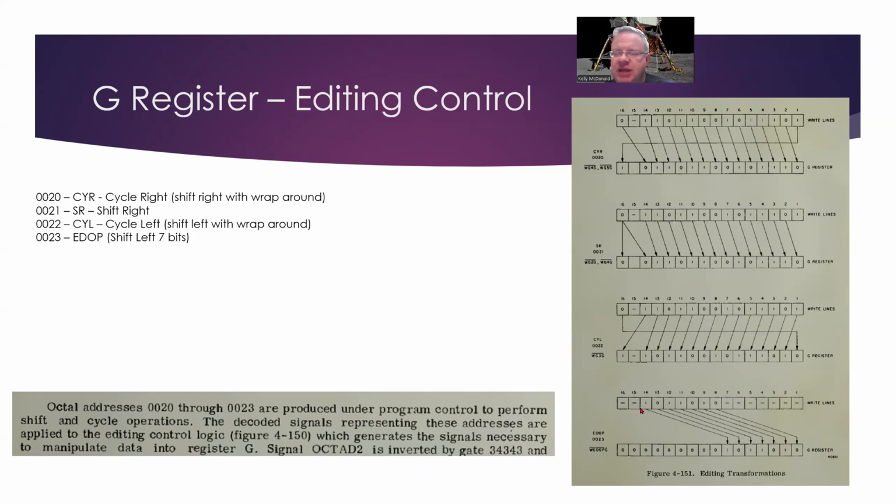When I started playing around with this and asking how I was going to build the logic to do it, I looked at whether I should use some shift registers. There are shift registers within the 7400 series that I could either shift left or shift right, and you can do the carry around. Each shift register, I think, was 8 bits, so I didn't need to use two of them. And I could get it to work fairly well for this scenario, this scenario, and this scenario, but not for this scenario because I'd have to do multiple shifts.